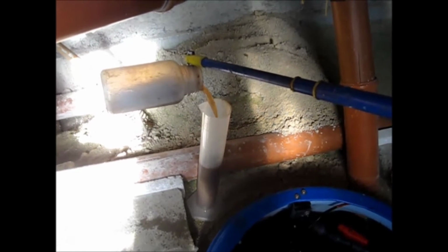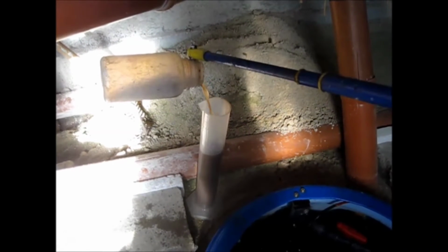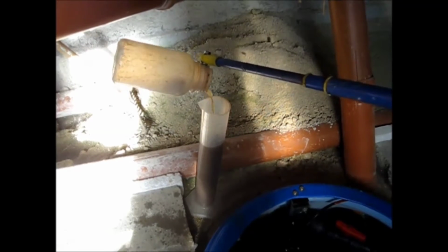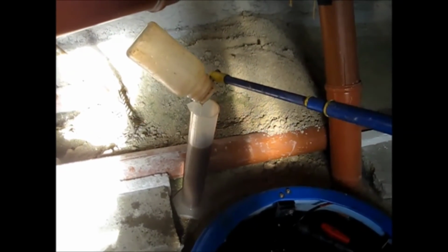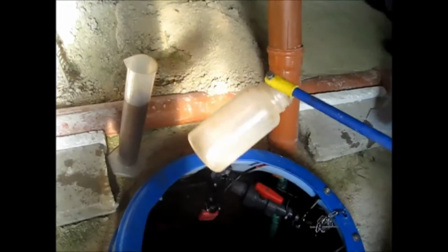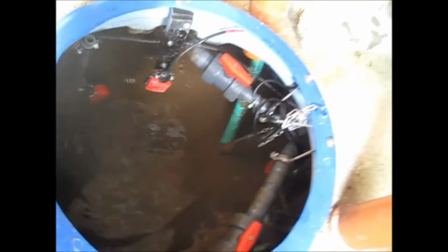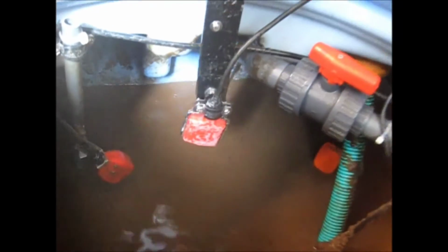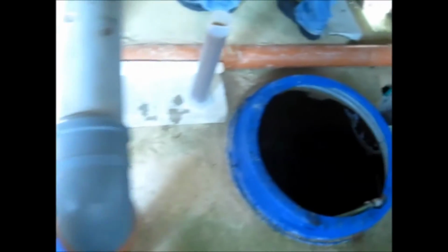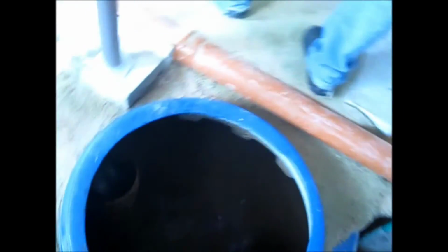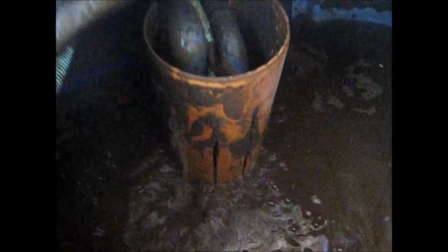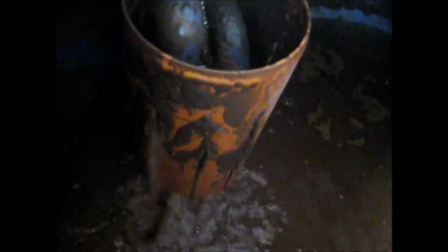After a certain amount of wastewater has been pumped into the second reactor, this process stops. Afterwards, a part of the content of reactor 2 is recycled into reactor 1. This is necessary for the wastewater to undergo the different treatment steps several times. You can see the recirculation water is also used to clean the grid in case it is blocked by some solids.